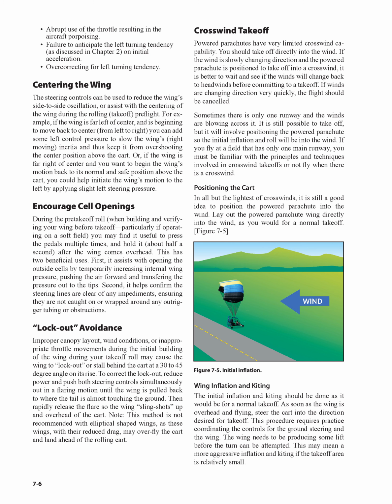If you fly at a field that has only one main runway, you must be familiar with the principles and techniques involved in crosswind takeoffs or not fly when there is a crosswind. Positioning the cart: in all but the lightest of crosswinds, it is still a good idea to position the powered parachute into the wind.